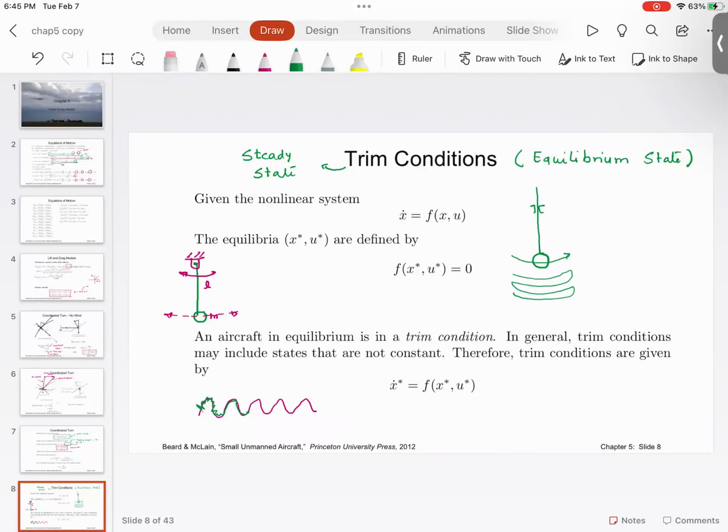There will be a disturbance, but the linear control surfaces will provide enough force and enough torque so that they can overcome this nonlinear disturbance and make this aircraft fly in a level flight. Everyone understood this? That is the goal of this development.